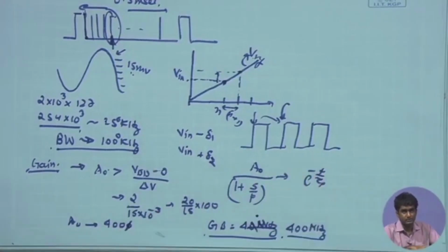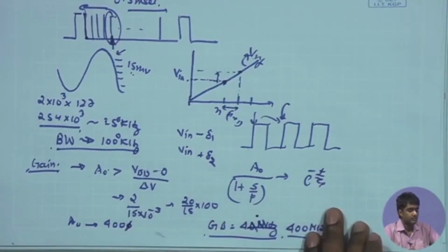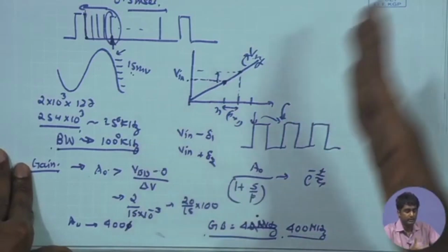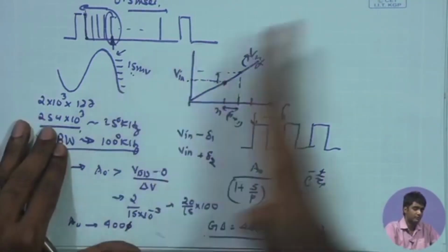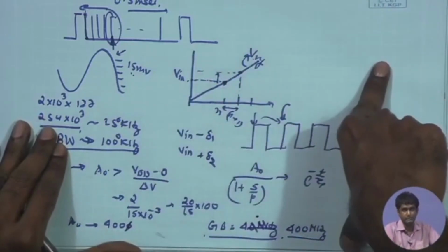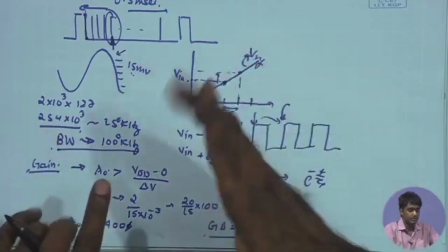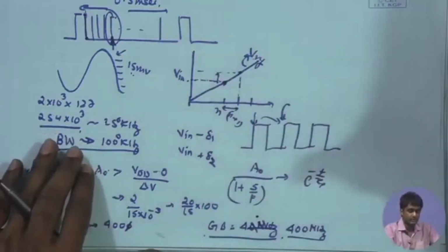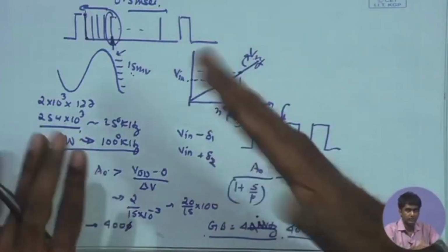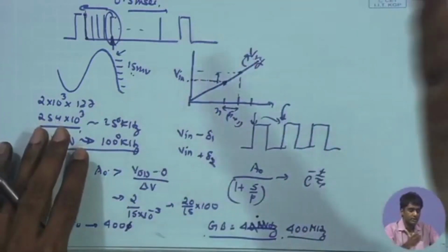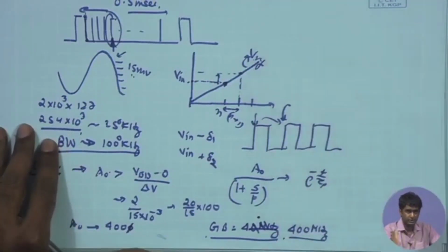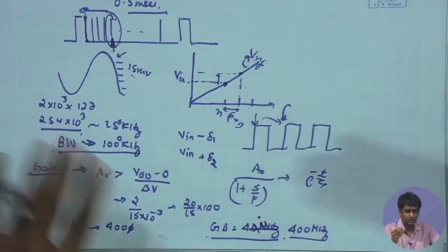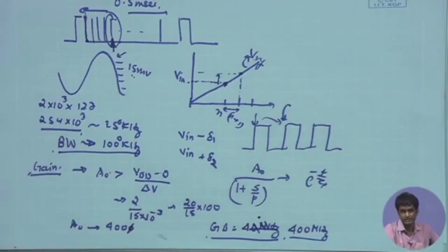Just like in the analog domain, if you are allowing up to 1 kilohertz, remember there also you may have to use a relatively higher chopping frequency, because you need to shift the frequency further higher as compared to the corner frequency. The corner frequency may be 100 Hz, but now you need to shift the signal frequency sufficiently higher, at least a few kilohertz. So that would also of course lead to increasing power in the front end stages.